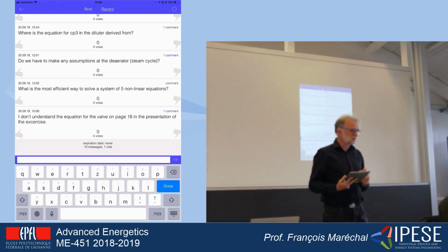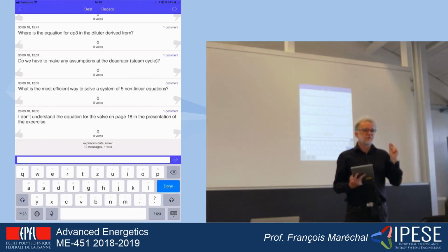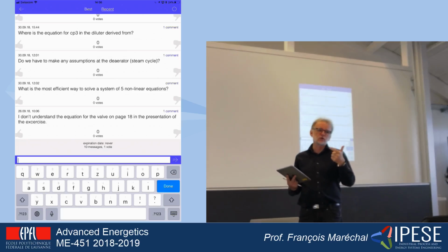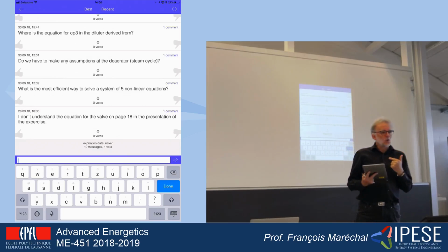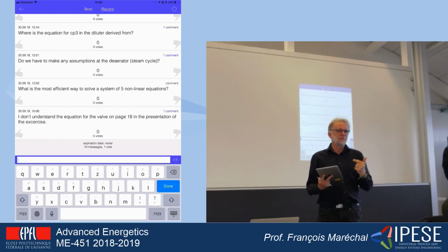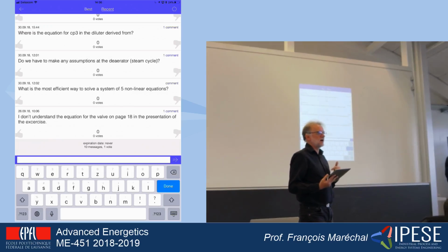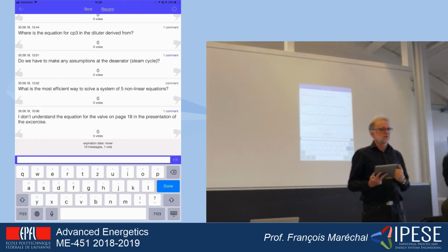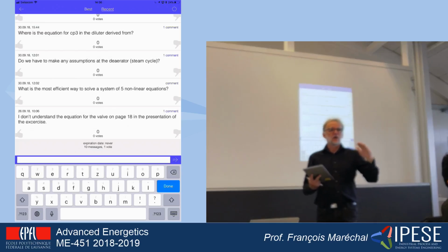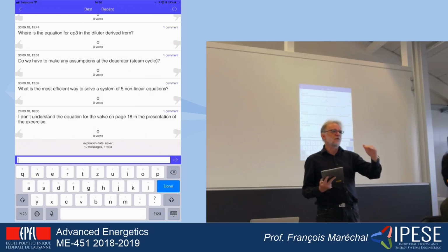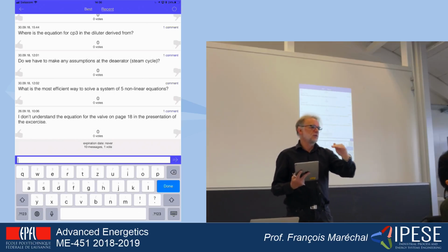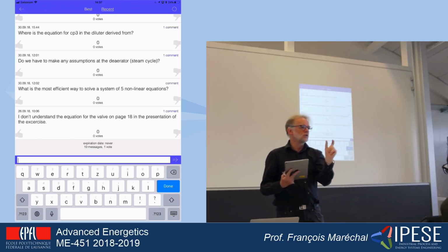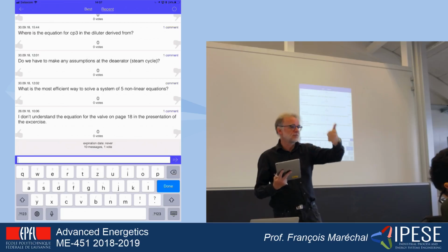In fact, in our case, typically we are working with flows, so mass flows and temperatures, which are related to enthalpies. When we write the equations of the mass and the energy balance, typically we are able to identify a sequence of resolution. It means that we are able to identify an equation that has only one unknown, and then knowing this one, the result is going to enter into the next equation, where we have two unknowns, one of which has been calculated by the first equation.